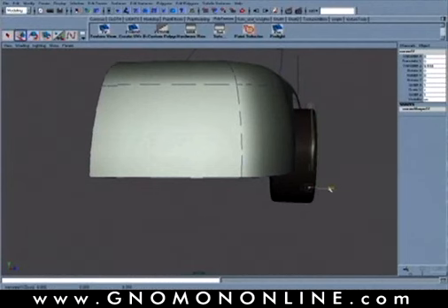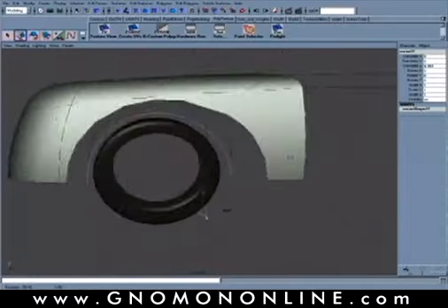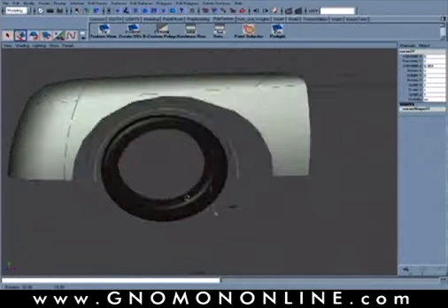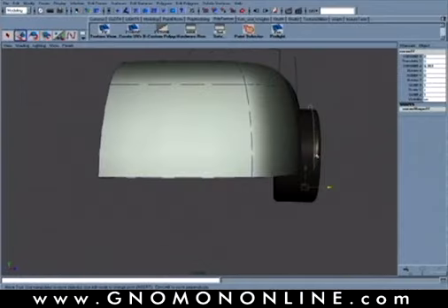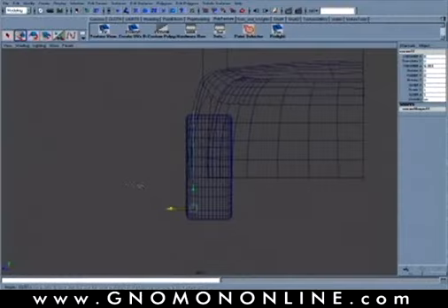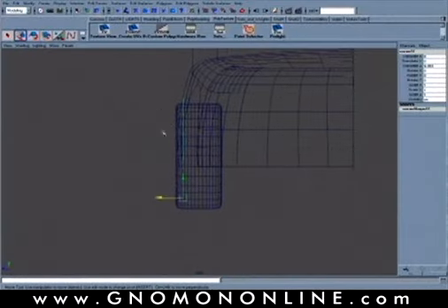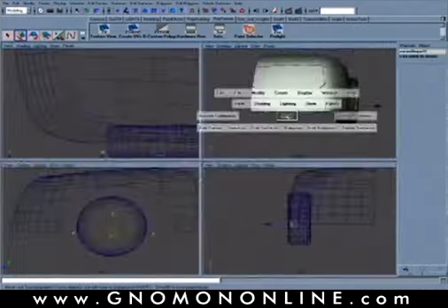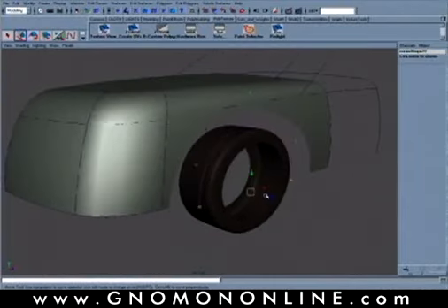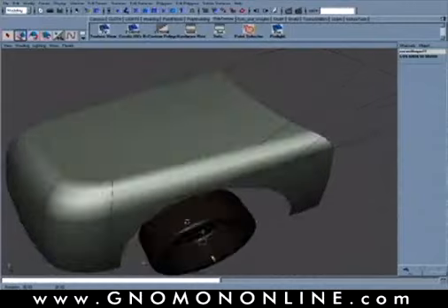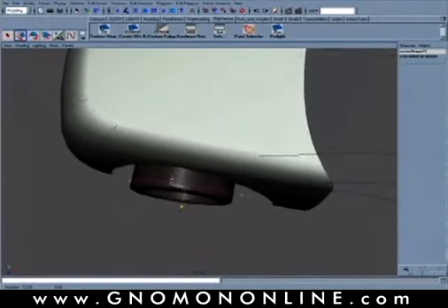In this case, I'll offset it enough that it does expose a little bit of the tire and will sit a little bit more flush with our other surface. This is pretty much a perpendicular line to that ground plane, so you may want to also arc this in a little bit too. If we go back to our CV curve, I may want to take a few of these points towards the bottom here and just translate those in or give it a little bit of curvature pulling back towards the middle there. Not too much that we're extending beyond the top view of our surface.